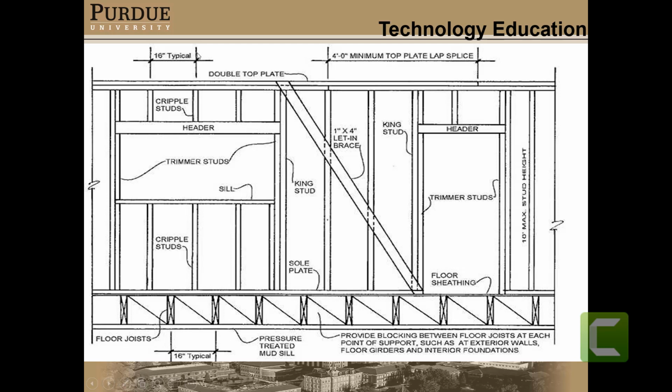You have to understand how forces work. The load on this window comes through this wall, comes through the cripple stud, which is still 16 inches on center, diverts through the header, hits the jack stud, king stud, goes all the way down, and hits the sole plate. These cripple studs underneath the window are doing absolutely nothing but catching drywall. It's holding nothing but the window. The window itself is not supporting weight, and if it does, you will have a crack through the glass, or you will have problems with it opening and closing. So those are your typical members.